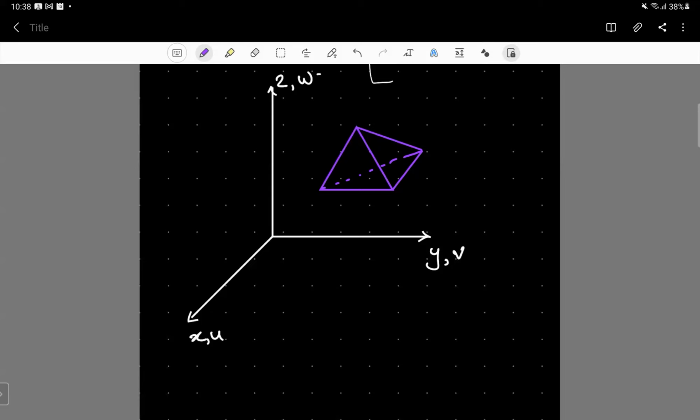When we are numbering the nodes, it's important to keep in mind that we number them such that we don't make any mistake while calculating the volumes. So we follow a certain protocol so that we don't get negative volumes when we do the calculation, due to the form of numbering that we use.